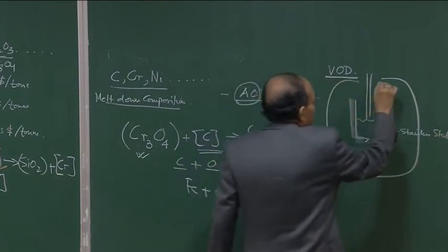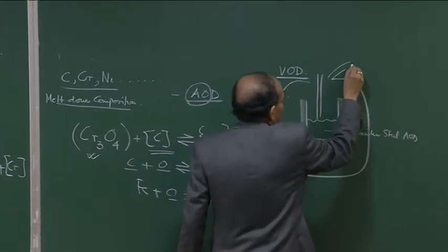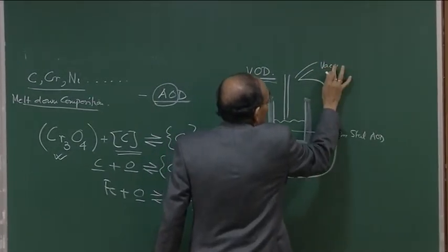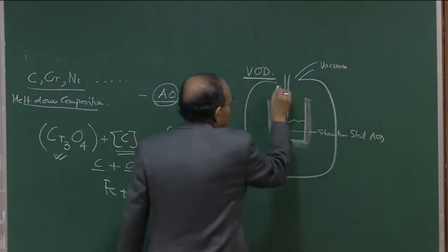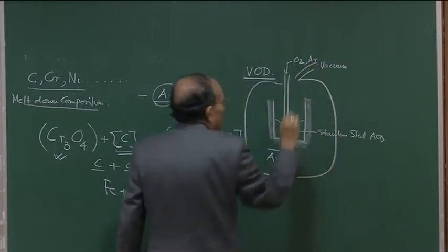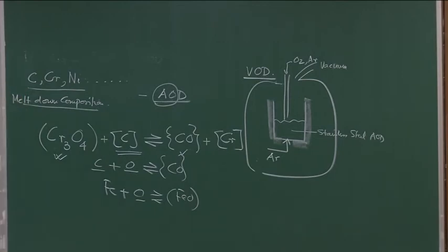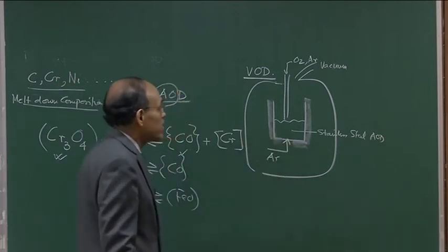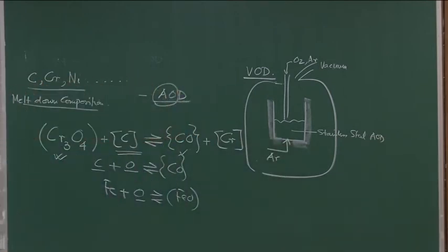It is sort of a tank degassing arrangement. So, you have vacuum, we will study that, and through this we will put in oxygen as well as argon. And you will have some amount of carbon oxidation here. So, you will have to have adequate temperature. Now that you have eliminated carbon with respect to chromium, you do not really require much higher temperature, because you have already created enormously high temperature in order to achieve preferential oxidation of carbon over chromium.